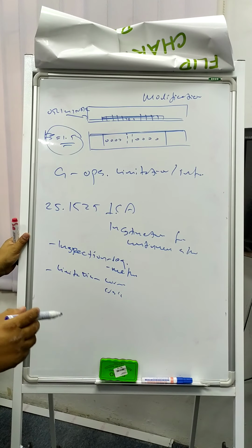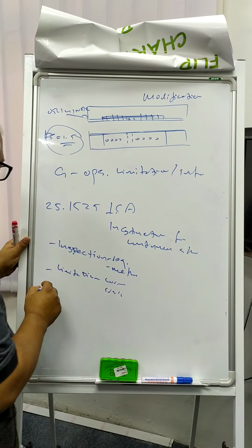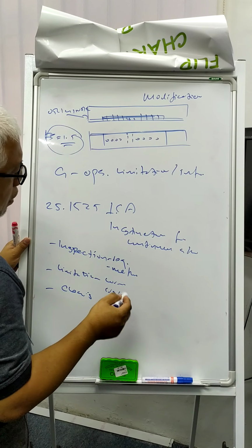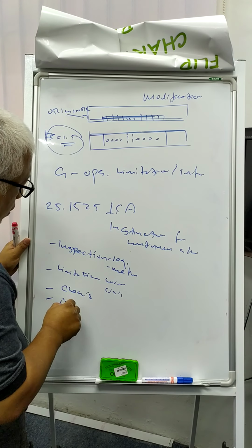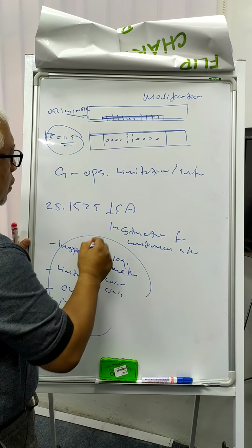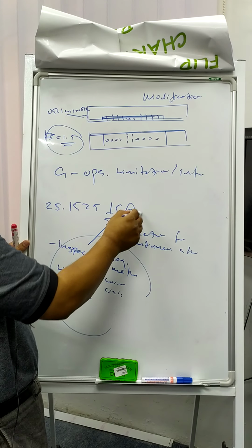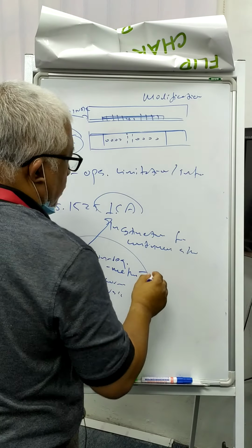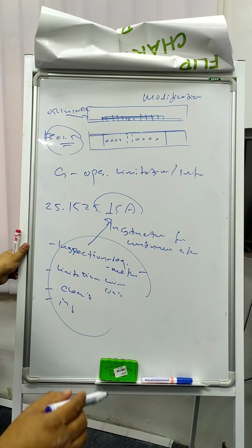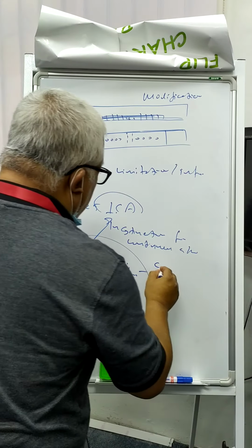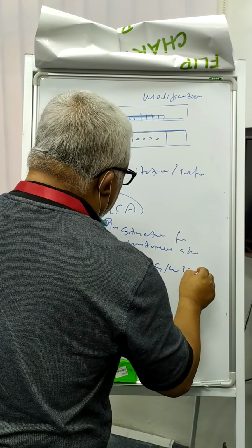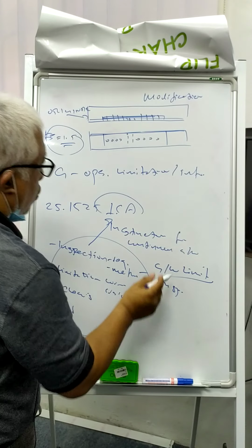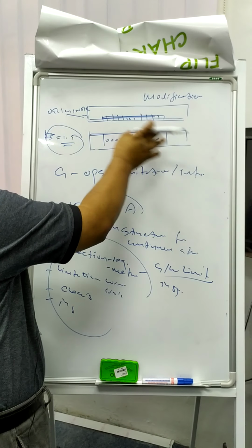So those are in the ICA, and how you clean the area if need be. Okay, cleaning. And then inspection method. So everything here is part of the instructions for continued airworthiness to ensure the repair is continually airworthy. Also time limitation. We call this the airworthiness limitation. The airworthiness limitation is the inspection interval. So how many hours until you go back and inspect this?